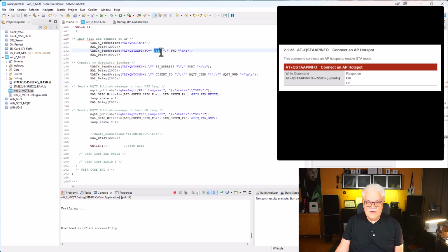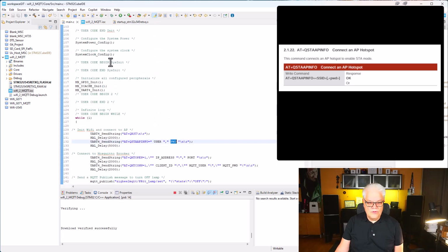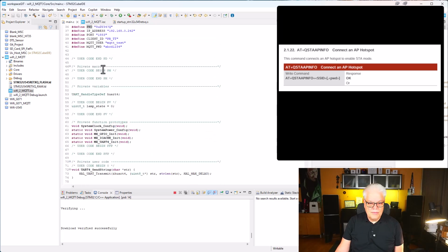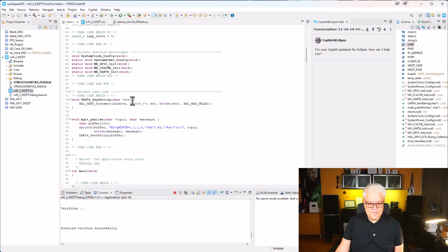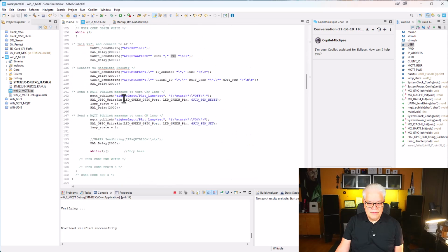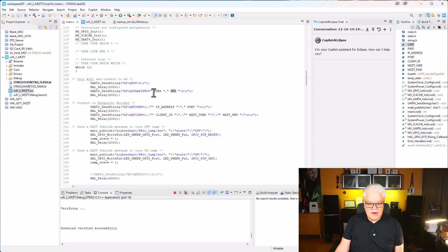The Wi-Fi has the user, that is the SSID, and this password is the password, and those were up here. So this is the information it sends there. I have the SSID PR Tech Talk, and this is the user password. So that will be sent there. And then we will wait for 5 seconds, giving my router time to send me an IP from my DHCP server.